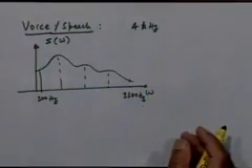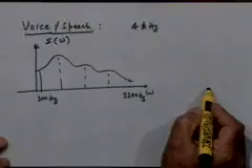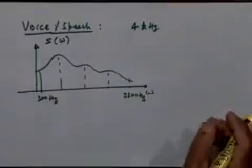But I must mention, this is not the actual bandwidth of the speech signal. The actual energy plot extends beyond this and goes on up to about 7-8 kilohertz. If you want really good quality, studio quality speech to be heard, you must process that entire band properly. But these are the standard values that we take in telephone communication. It's found to be adequate. Now before I leave this signal, I'd just like to say a little bit more about it.